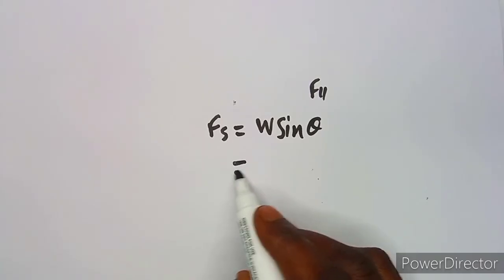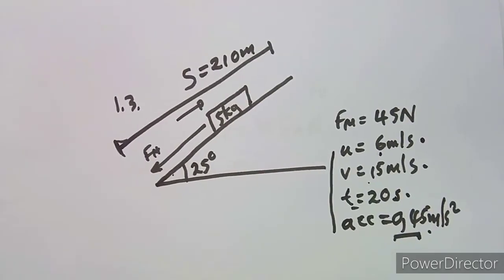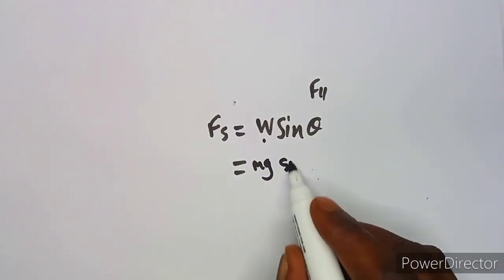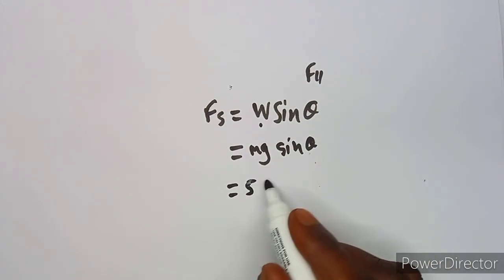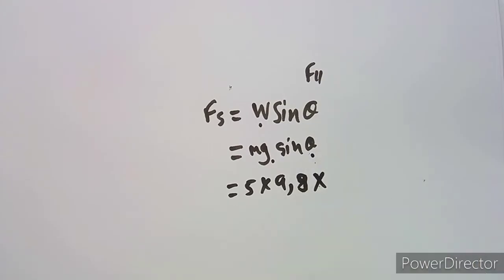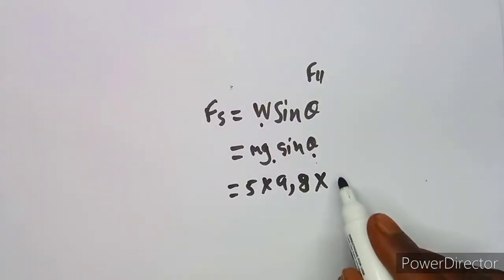I think this one we are now used to from our friction, from this part of N2 engineering science. We can relate from that one. So this is the mass, mg. Remember w, that's mg sine. Let me just write the formula before we substitute. So we've got mg sine theta, m, which is the mass 5, times the gravitational, which is 9.8, times sine theta. The angle operating in the diagram here is 25 degrees, so that's sine 25 degrees.